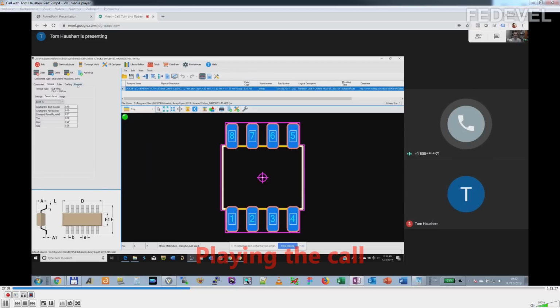Well, no. We did test with the Japanese, and they made test boards, and they said, guess what? If I make a board with an SOIC or whatever kind of quad flat pack you want, and I use the most density level, and then I run it through all these stress tests, vibration, thermal cycling, then I create another board with a nominal density level and run it through the same tests, they got the same results. So the most density level and the nominal density level did not produce any better results.